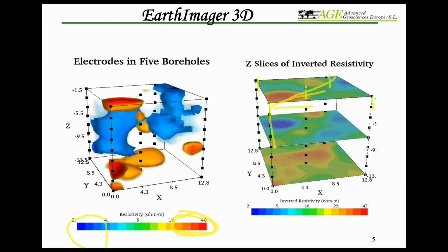Let's say you're looking for aggregate mining. You want to know how much overburden material you need to remove, and you know the resistivity value of that material. You can render that information with the related resistivity value, and you will see how many cubic meters of material are estimated in the area.